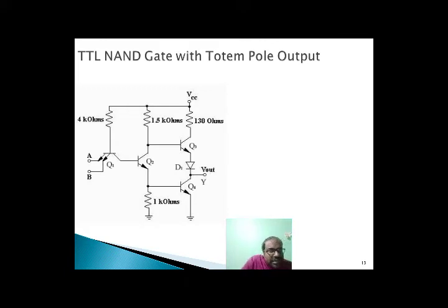At the same time, the collector of Q2 is at a low voltage level to keep Q3 in off condition. By seeing this, we can summarize all the input and output conditions. When the diode is not present, Q3 will conduct slightly when the output is low. To avoid this, the diode is connected, which keeps the base emitter junction of Q3 reverse biased.